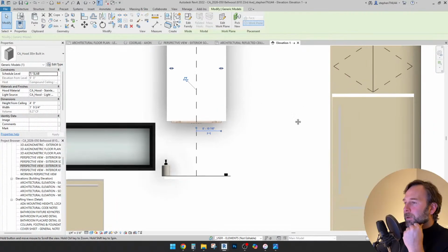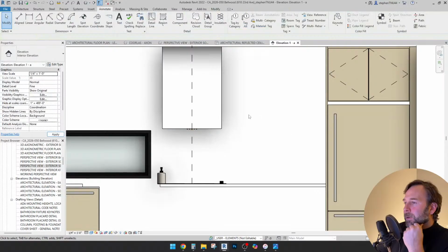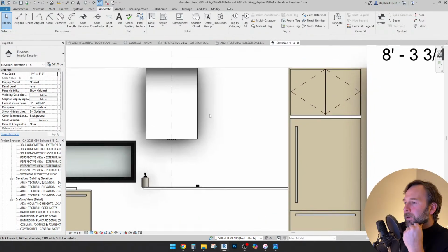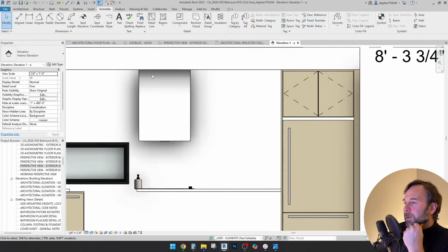This keeps happening because we have that goofy offset with a 3/4 inch difference. So I have to raise it up a quarter of an inch to tuck it in there. And the reason I wasn't sure if I wanted to center all this is because it could leave you with some really odd cabinet widths and wasted space, and we don't want to get into custom stuff.